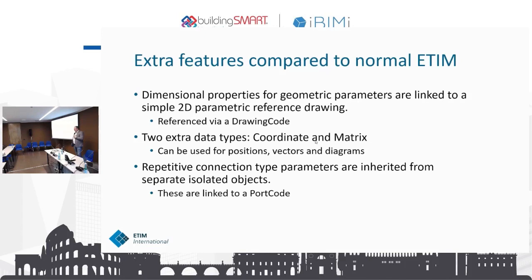And we also quickly discovered on the HVAC side, if you have a fitting with 4 connections, and it could be flanges or threaded connections, these are all standardized and they are reused. So we had threaded connections in 100 different classes. If something changed on the definition of these drawings of the connection, we had to issue 100 RFCs. So we thought that's a redundancy that we have to kill straight away. So the connection types are also modeling classes in themselves, which we refer to in the actual modeling class.